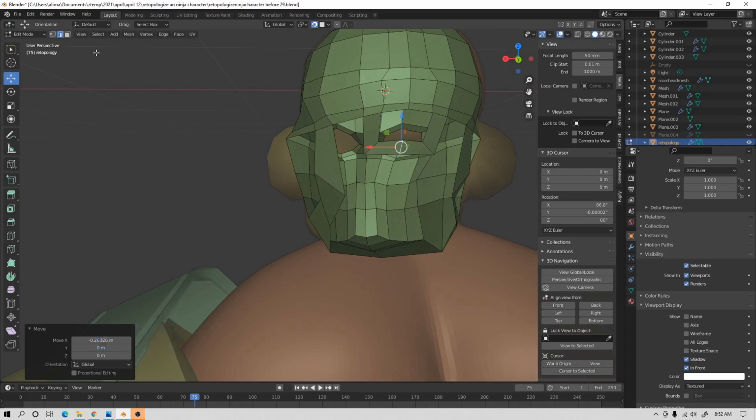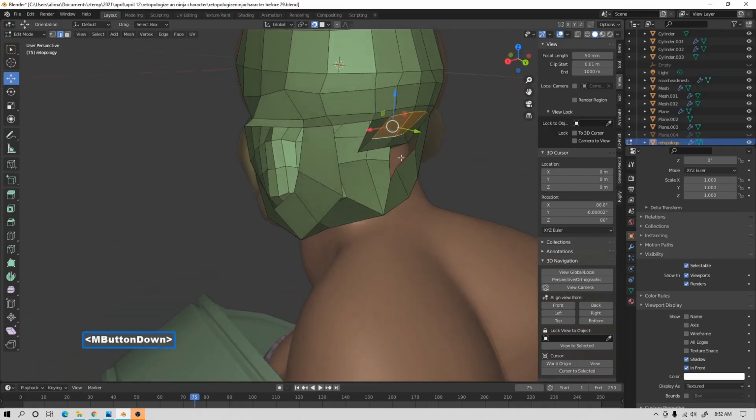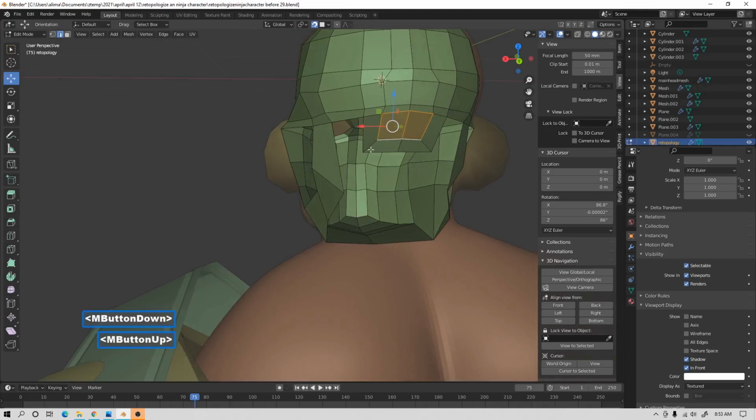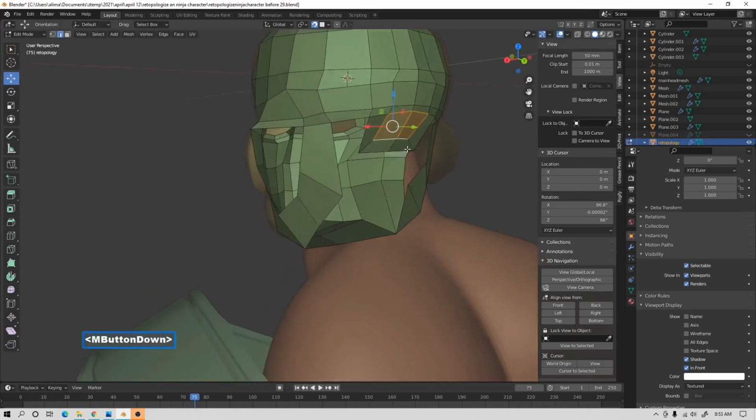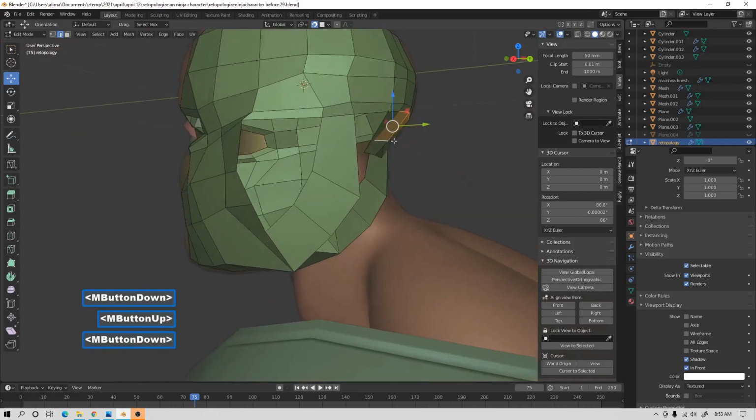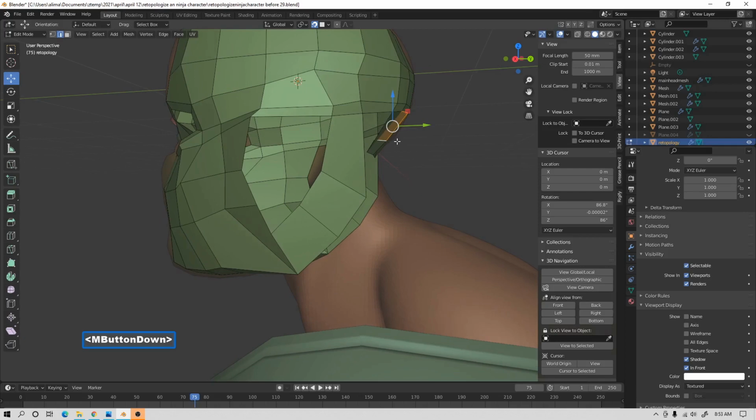With that done, we'll select here, hold Shift, select here as well as here, press F. If you're wondering why we're doing this, see right here, there were 4 faces. By doing this, when you look down to the bottom here, now we have 2 faces, or 4 edges, I should say. Now there's 2 edges. So we effectively reduced the geometry.